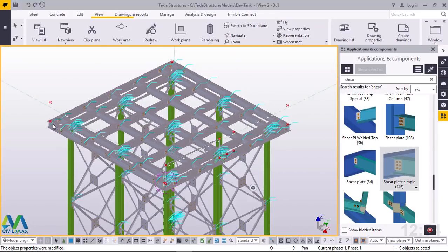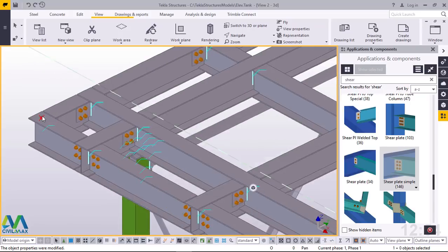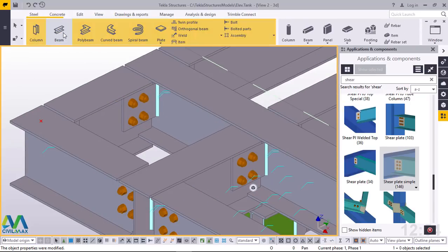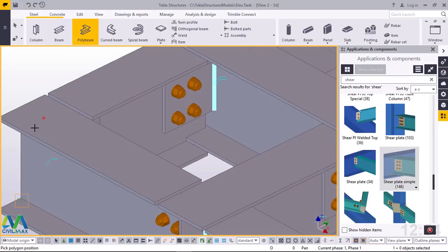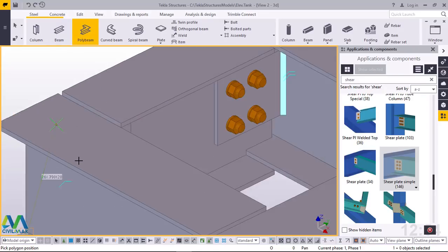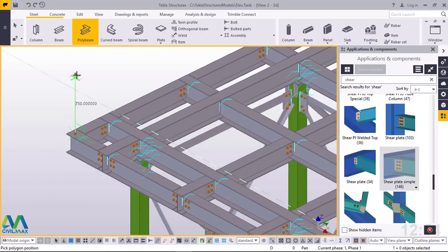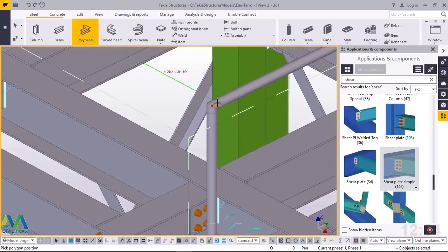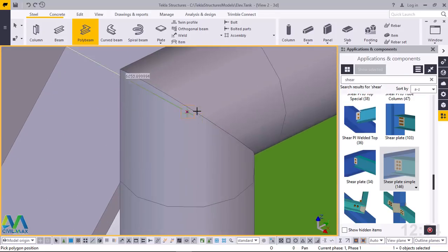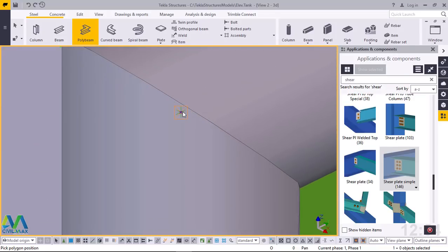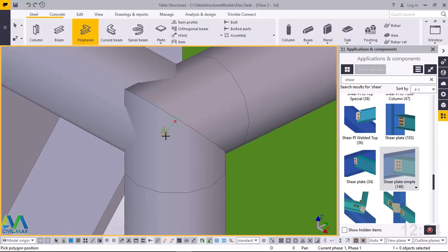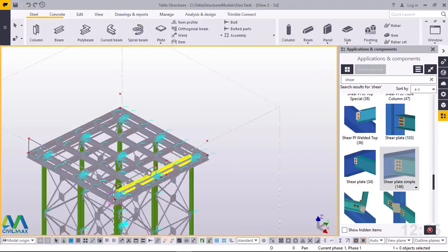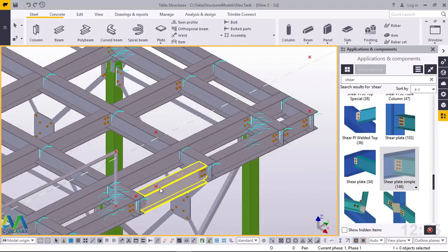We'll do the same thing to this end. We'll come all the way and come to steel here and click polybeam, and we'll snap right here and target that height of 800 and snap on that spot, and we'll run all the way and snap right at the center of that spot and press our middle button on the mouse, and that will be the proper guidance in creating our handrails.